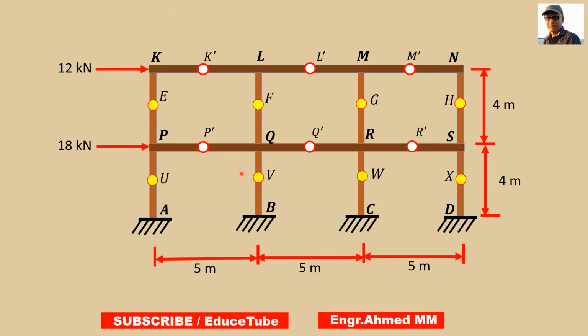Third assumption, the axial stress in a column is proportional to its distance from the centroid of the cross-sectional area of the column at a given floor level.